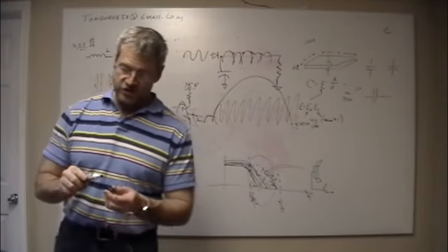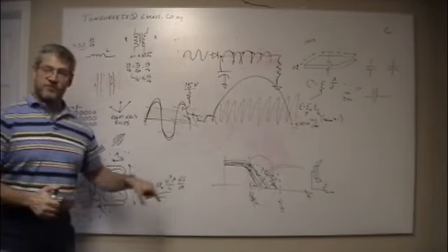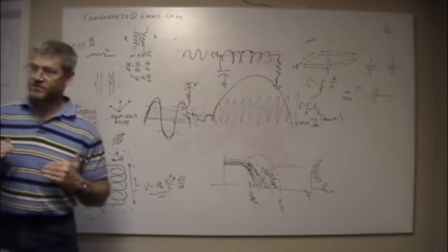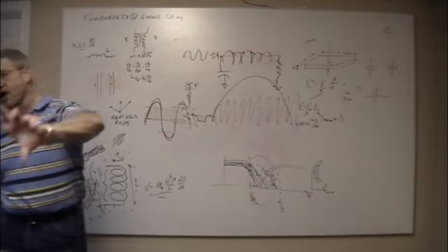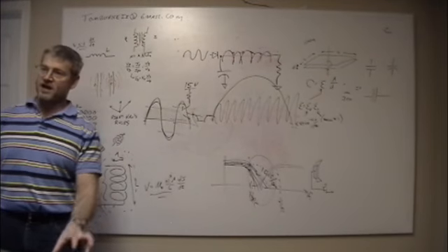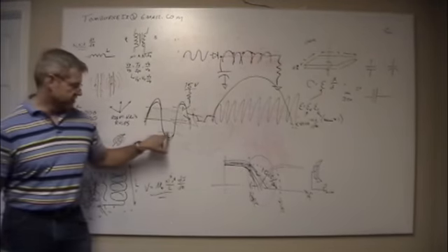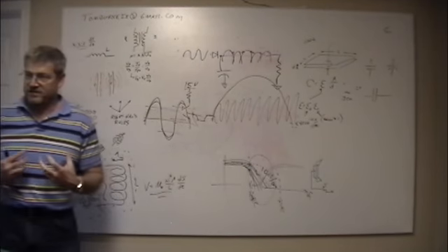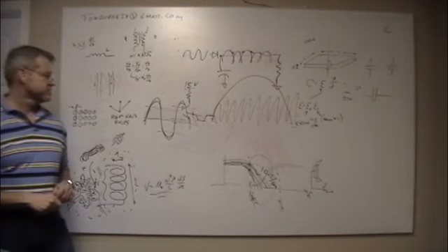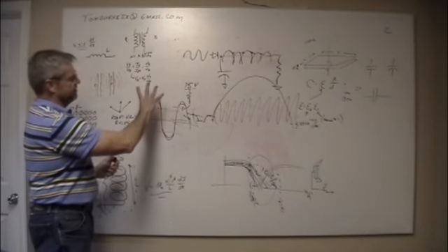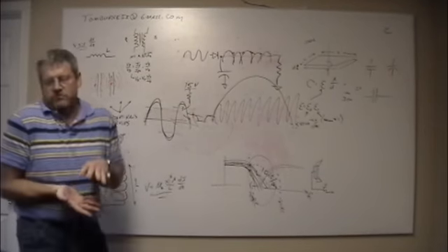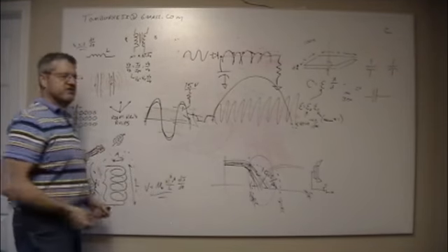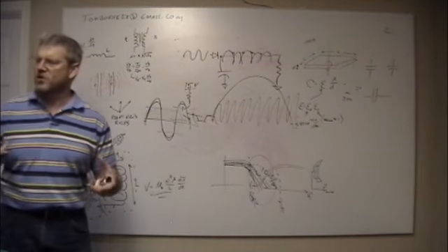Mm-hmm. So the truth is, the transistor amplifier is better as long as you use it inside the realm that it's intended to be used. As soon as you start overdriving the thing, the transistor amplifier just cuts it off, and oh God, it's this grating sound, right? That's this third harmonic that just hurts your ears. But the tube amplifiers, they lose linearity, but they don't just cut. So it gives them a sweeter, a warmer sound.